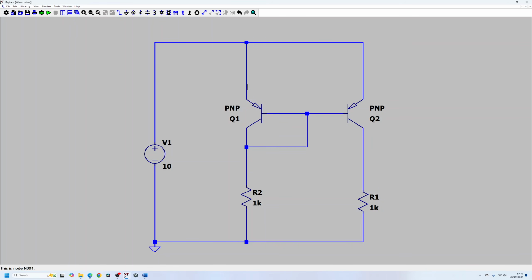looking at the current. So you can see for a PNP transistor, there's a current flowing in this direction, but there's also current coming out from here, flowing down to here. There's also current flowing from this direction down to the load resistor over here, but then there's a small amount of current that's flowing in this direction. If you look at your NPN transistor gain or current gain, it's basically IC, the collector current, which is flowing out from this junction, is equal to the base current times the gain of the transistor, which is typically known as beta.